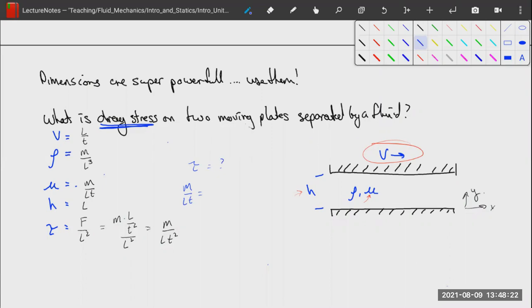And it requires a little bit of understanding about the physics of fluids too, which is one of the main reasons why you're taking this class, to get an intuitive feeling about how the physics works. You can imagine anyway, if you're taking two plates and sliding them past each other, does density or viscosity matter more? And remember, viscosity is how thick something is, how viscous something is. So honey has a much higher viscosity than water. So if you put honey between two plates, or water, which is going to have more shear stress when you move them at the same velocity, right? Or does density matter more?